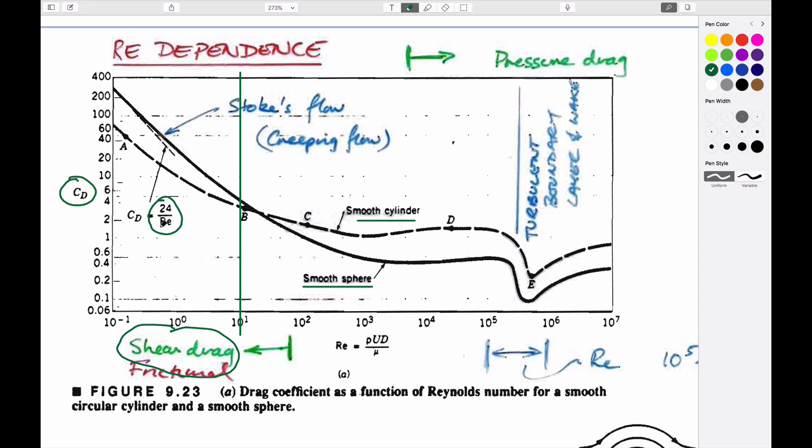One thing we'd like to calculate would be the magnitude of the forces that are applied to a structure, lift or drag. You could imagine a wing going through the air at a certain velocity, and if you know the drag force which is applied, the product of the drag force times the velocity gives you the power that you have to push through.